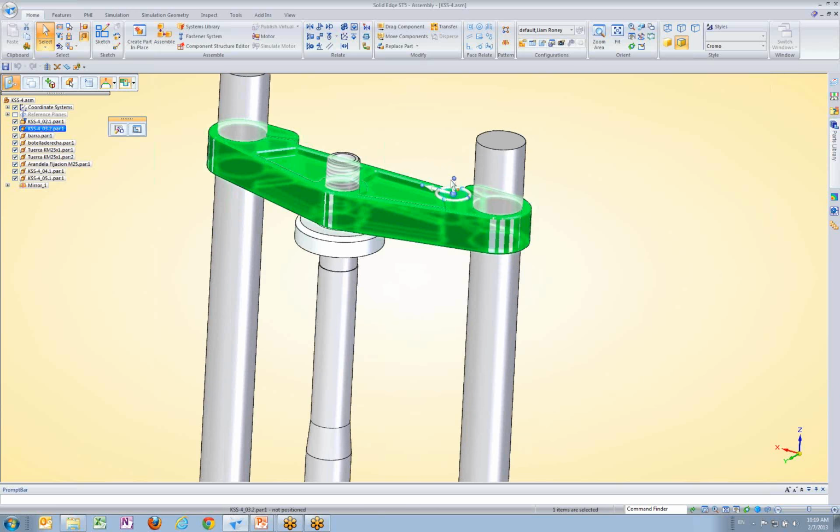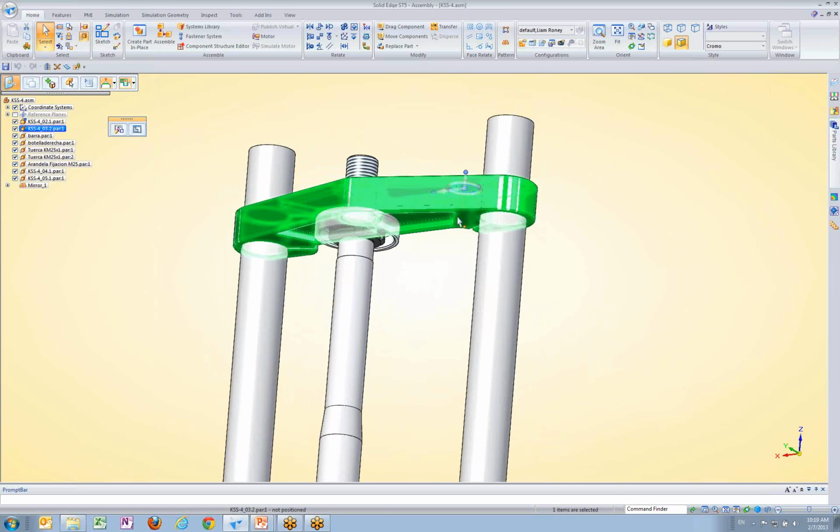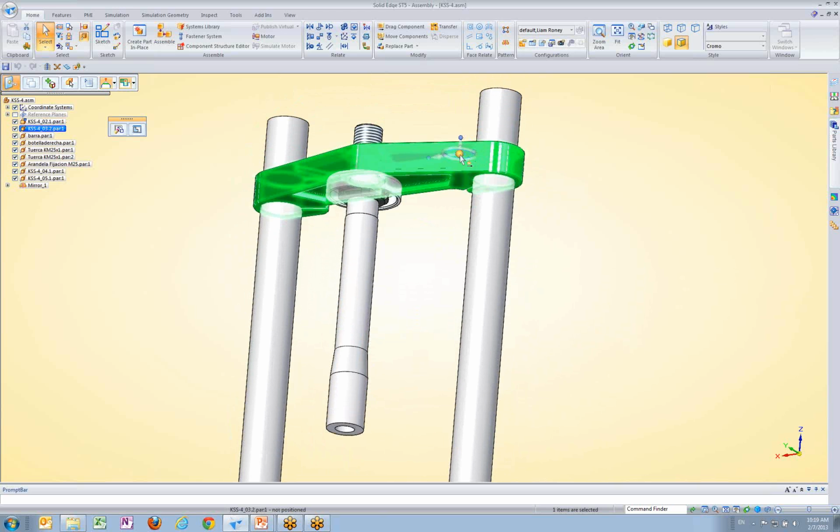In this case, we want to start by picking our control point. Because we want to line up the bottom of this bracket with the bottom of this piece here, I want to click on that center knob of my steering wheel. Just click once so it's on the end of my steering wheel. And then I want to bring it around and just snap it to any face that's on the bottom there. You can see that it'll swing my vectors around to adjust to that face. It usually will put a vector normal to the face. Again, if you need to make changes, you can use these directional nodes to make those changes. But now we've got a vector pointing down, which is where we're going to move this.